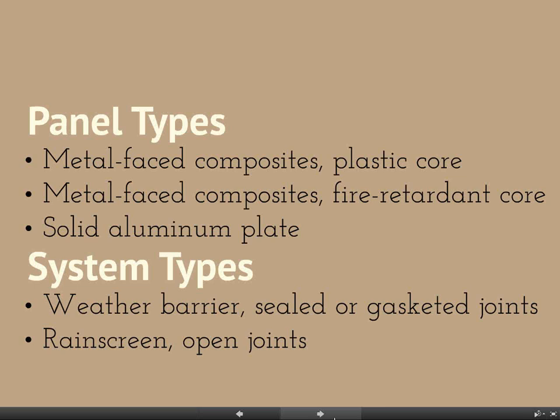One of the things that has been coming up with the rain screens, it was almost as though it was a revelation to some of our clients that, with the open joints, it's actually possible to see the continuous insulation behind the rain screen cladding. I just this week had somebody send me a photo, and it looked like they designed the cavity with virtually no space between the cladding and the insulation. So the insulation surface was right out at the joint instead of back in and in shadow. So be aware of it. Be careful if you don't want the yellowish insulation showing through.